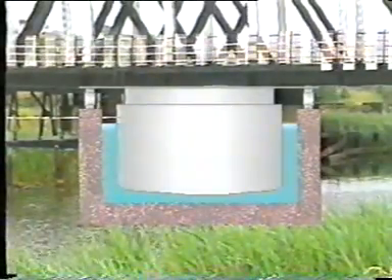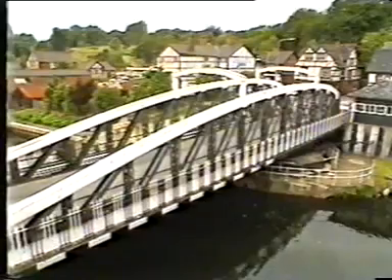Another application of a pontoon can be found in a swing bridge with a rim bearing. The pressure on the rollers, due to dead load, is reduced to about 30%. In this way, friction is reduced, and consequently, the energy necessary to move the bridge. At the turn of this century, this system was used in some large swing bridges in England.